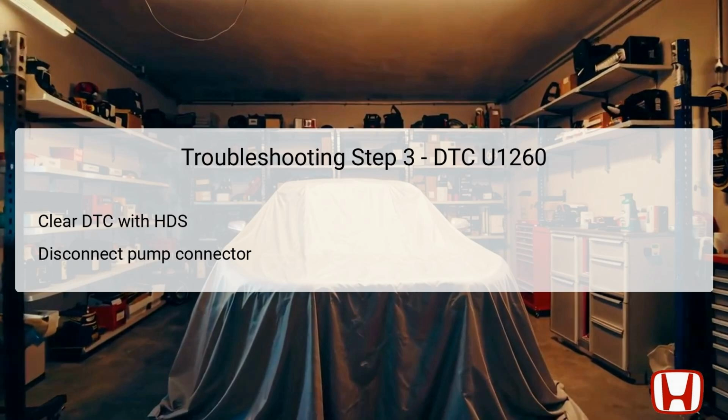This step is critical as it helps identify whether power is reaching the auxiliary fluid pump, which is essential for its function. In step 4, the technician will again measure the voltage between 2 specific test points. The conditions dictate that the vehicle must be in on mode, with the auxiliary transmission fluid pump 4P connector still disconnected. This measurement helps determine whether the power circuit is functioning correctly.